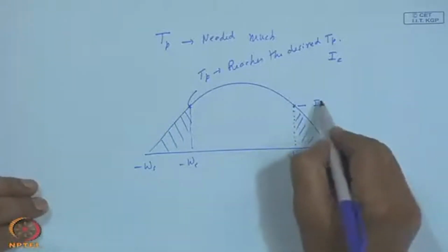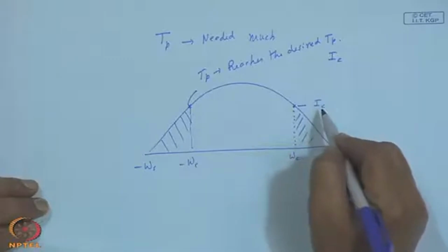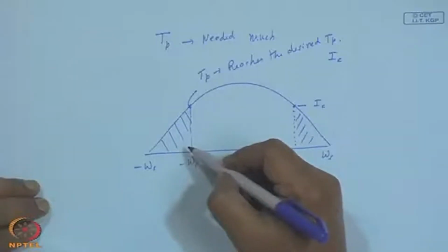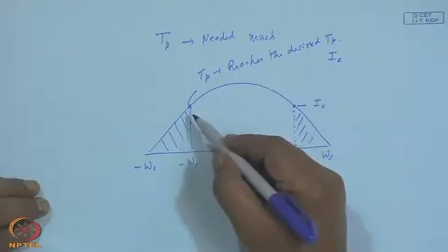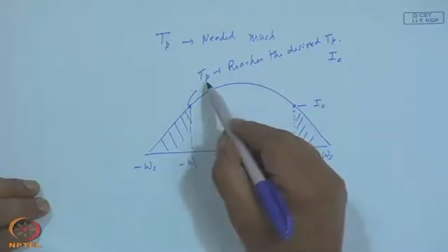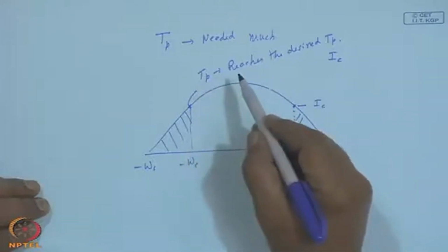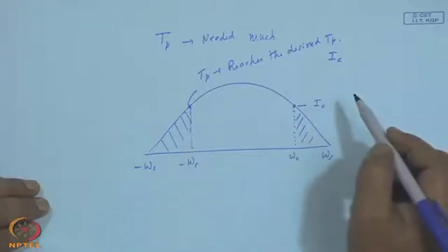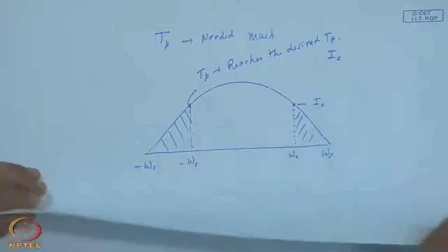Of course, unless the solar radiation is at the critical level of radiation IC, it will not deliver the energy at the desired temperature. But if the energy before that is not sufficient to heat to the temperature required of Tp, it cannot supply the energy at the temperature even if IC is reached. The other way around is not possible.